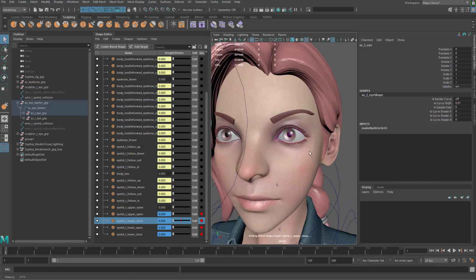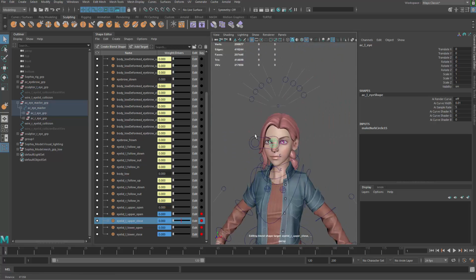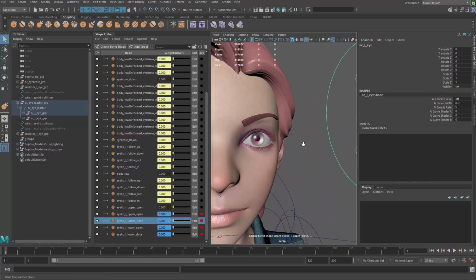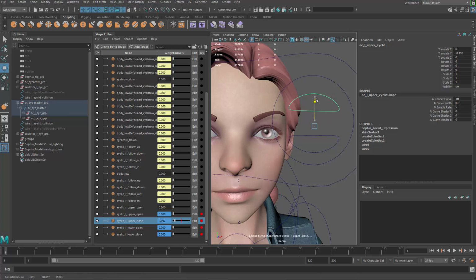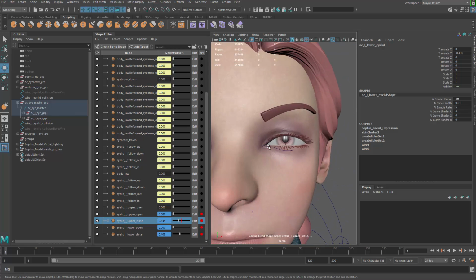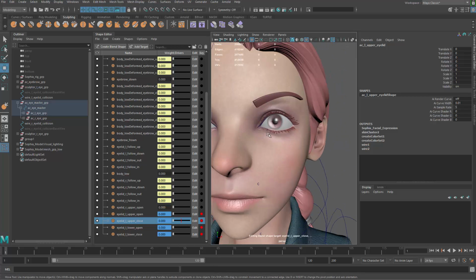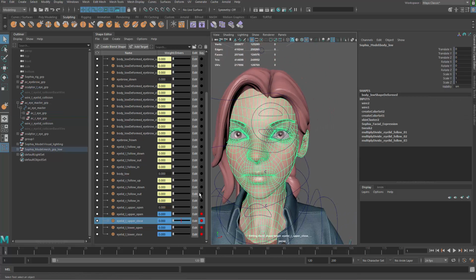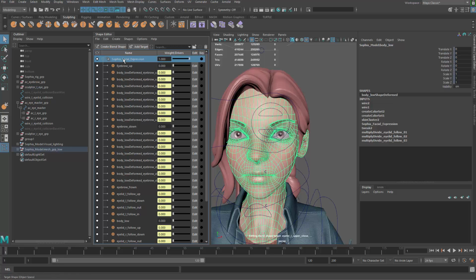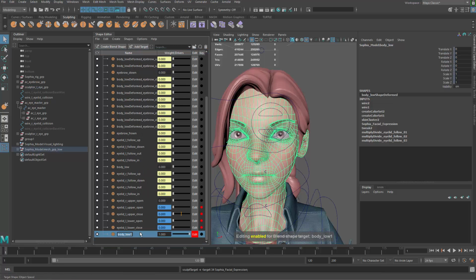Another thing I want to do, the final eyelid movement that I want to have, is a sneer movement. Now you could assume that the sneer is just the eyelid getting closer like that, but that's a very relaxing pose. What I really want is actually pushing in. The muscle is really trying to squeeze the tissues around the eye to go in. So let me do one more blend shape. Grab the blend shape and add target, and this one will be my eye left sneer.